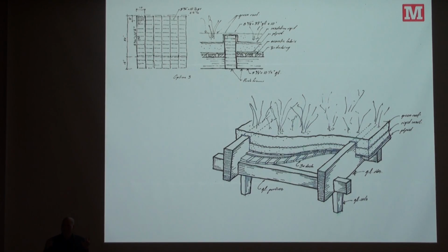And then if I zero in on this, and I started imagining the structure, what we have are the glulam ribs that undulate, the purlins that are faceted, that accommodate the undulation. Even right in here, this is the structural decking. Now the structural decking has been opened and spaced, and there's an acoustic material on top of it.